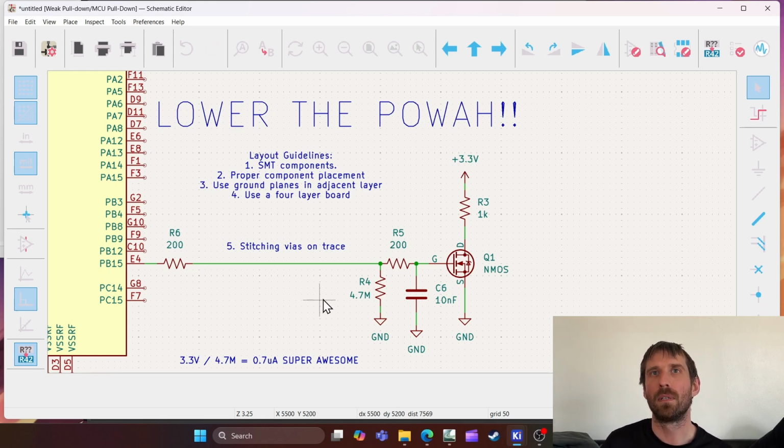So in general, this is how you want to do it. This is a low noise design, and I think, listen, if you want better battery life, you got to do one of two things. Get a bigger battery and incur all that cost, or decrease the current that your device is using. So because this costs pennies, along with the time to do a good layout, I think this is probably where we're heading, of using higher values. So I am very interested to see if this actually works in real life.